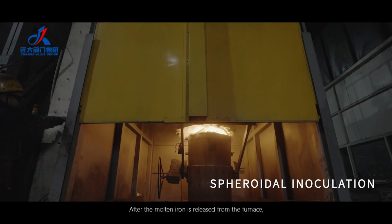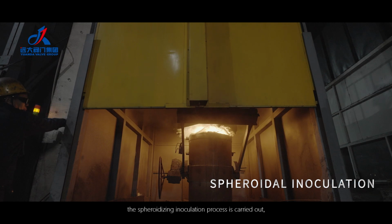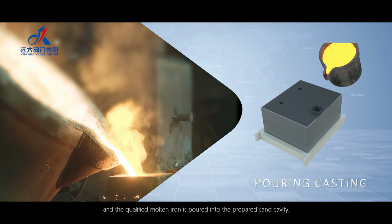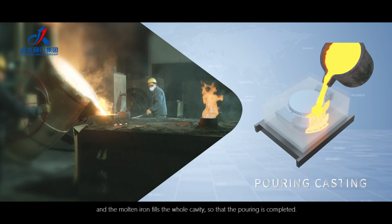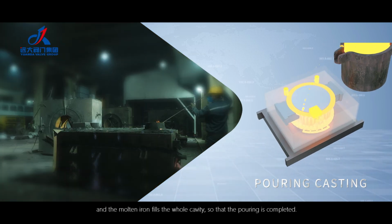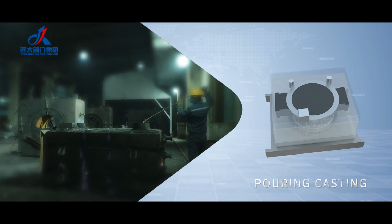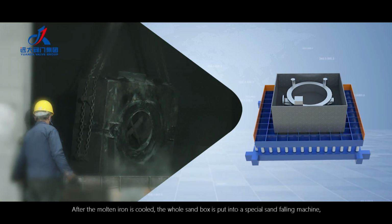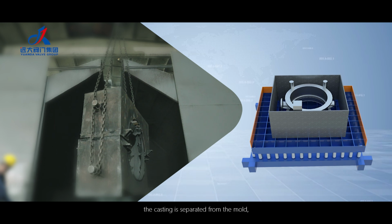After the molten iron is released from the furnace, the spheroidizing inoculation process is carried out, and the qualified molten iron is poured into the prepared sand cavity, and the molten iron fills the whole cavity, so that the pouring is completed. After the molten iron is cooled, the whole sand box is put into a special sand falling machine. The casting is separated from the mold.